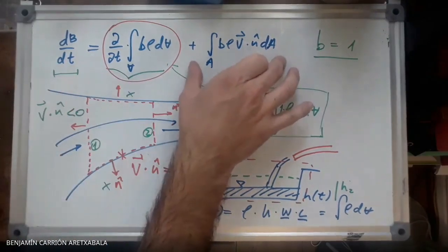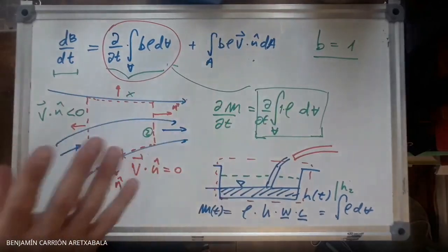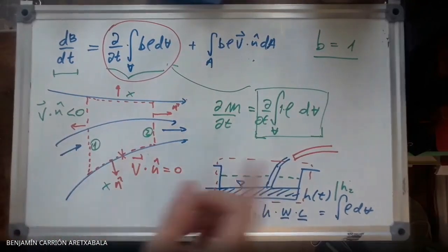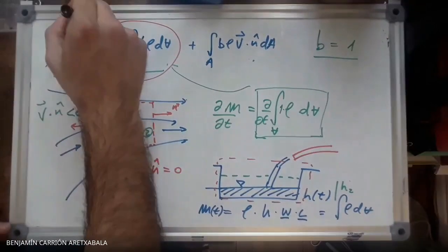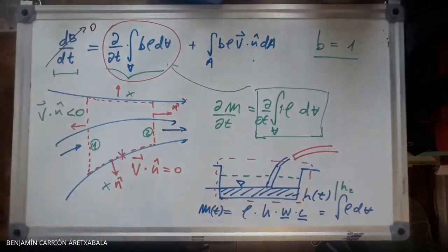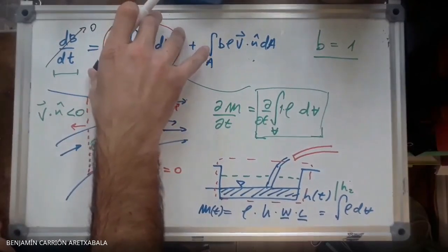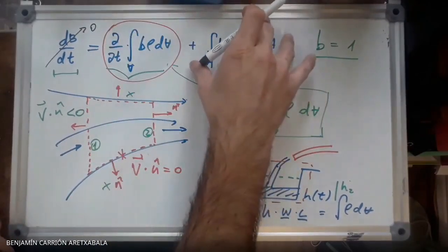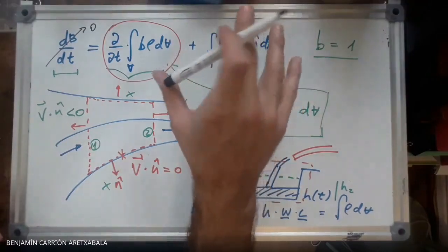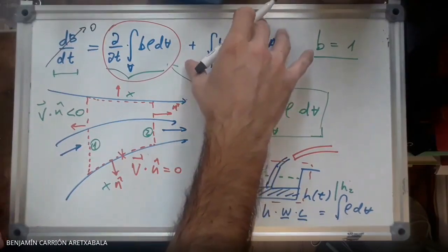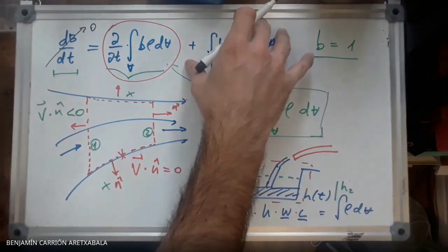This is saying that the total change is going to be equal to the change inside the control volume plus the fluxes. Okay. And here's when you need to realize that if we're talking about mass, this guy is always zero by definition, because mass can't change over time in a system. So whatever changes inside the control volume has to be equal and negative to what is coming in because of the fluxes of that property.